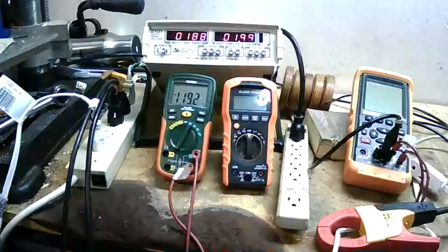That 2 amps flowing is what I was talking about when I started this. This is pulling 2 amps when it's not drilling. And when I drilled, it went up. I was drilling hard into that wood with a 1/2-inch spade bit, and it was getting up to maybe 2.4 amps. So it's a very inefficient, very high loss device. Let's write these down.